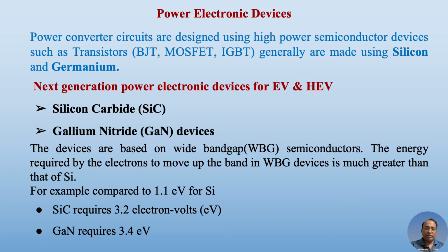Just now we have checked the different types of power converter circuits or electric circuits that will be required in an electric vehicle for the overall control and operation. So just to revise, those were of categories AC to DC converters, then DC to AC converters, then DC to DC converters. These are the three major categories of converters.